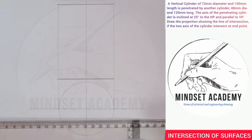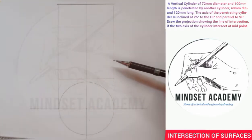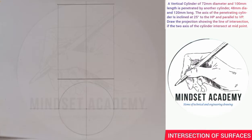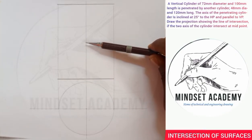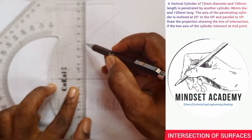Now, this is the plan, this is the elevation, but this is a cylinder, and we're told that another cylinder penetrates this cylinder. The length of that cylinder is given to be 120 millimeter, and the diameter is given to be 48. So a smaller cylinder is penetrating this at an angle of 25 degrees. Another keyword is that the center of the penetrating cylinder meets the center of this other cylinder. So this center here is half of 100, which is 50.